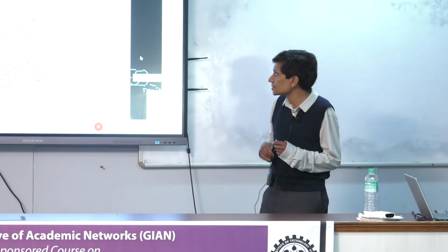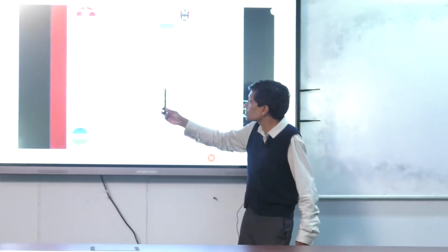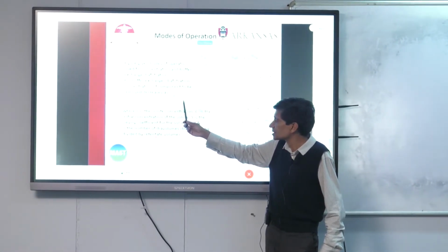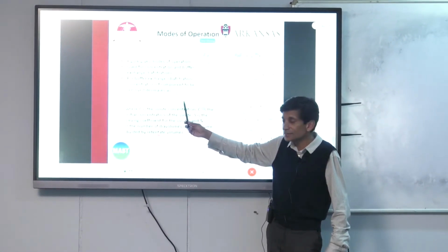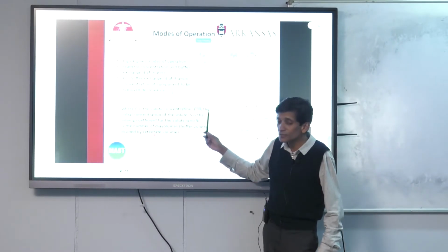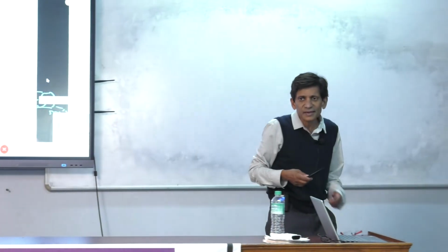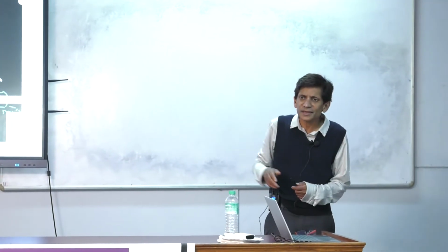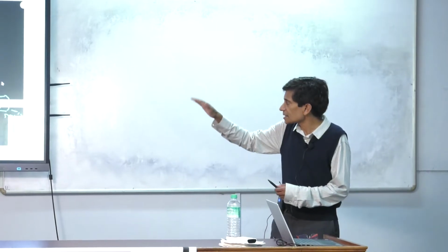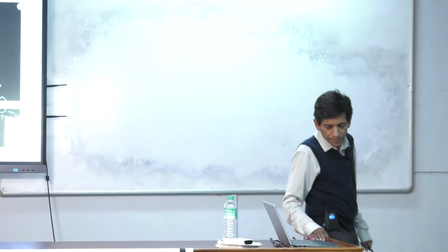If you're interested, come and see me. But anyway, what this means is that after 1 diavolume, you have lost about 63% because it's 1 divided by e. After 2 diavolumes, more than that, and so forth. And so typically people run this for about 7, 8 diavolumes till you remove about 99%. But that's very easy to model mathematically, and that's how that goes.